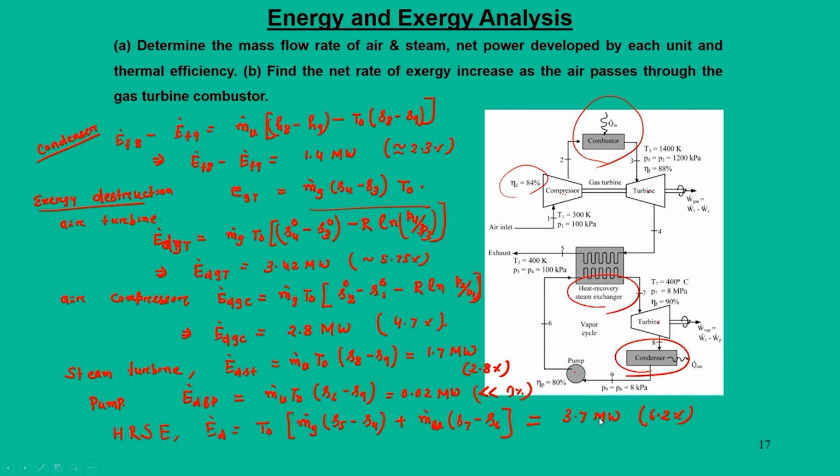Energy analysis is quite justified, because the cycle efficiency of the combined mode is always higher. Exergy analysis also tells us that the exergy loss at each component is quite minimal, less than 6%. Hence, the combined mode of gas turbine operation with a steam unit is quite possible. So, this is all about the combined power cycle.